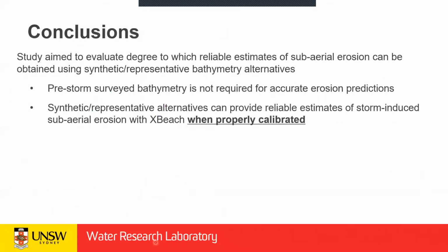So with this study, what we aimed to do was to evaluate the degree to which we could obtain reliable representative bathies. And what we were able to identify was that we don't necessarily need pre-storm surveyed bathy to carry out operational forecasting, but we can use synthetic and representative bathymetries and get erosion estimates similar to what we would have obtained if we had used the pre-storm surveyed bathy, as long as the XBeach model is properly calibrated.